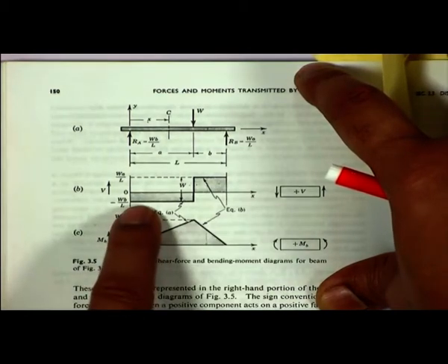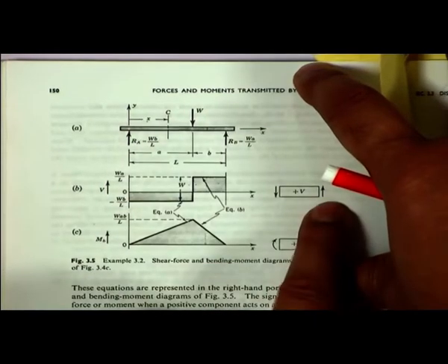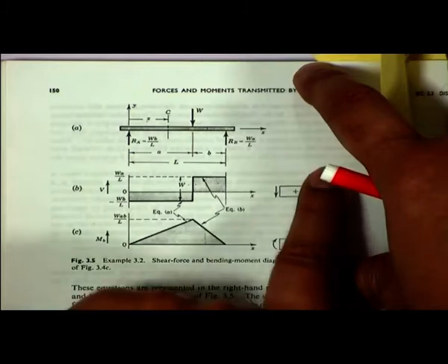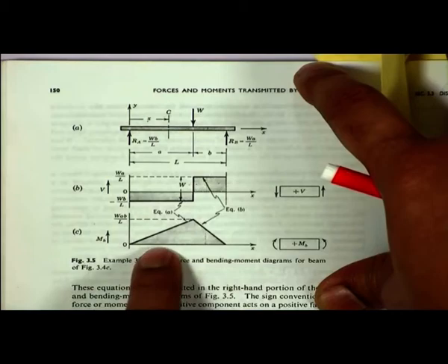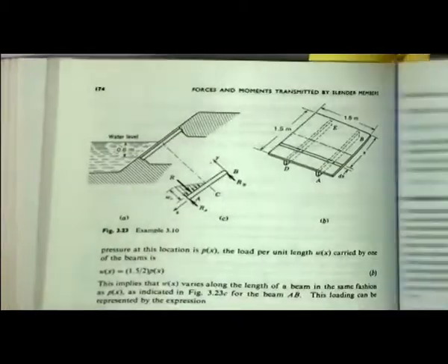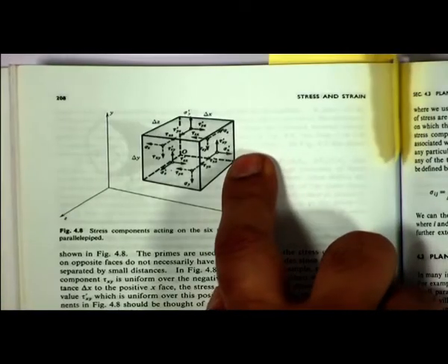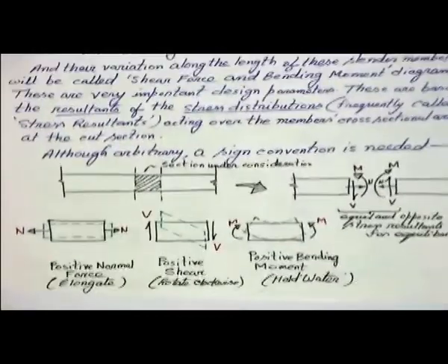It is drawn as negative shear below the line. Similarly, this force which is creating the right part up is drawn as a positive shear force, and this is the bending moment. Probably this is reversed, but it is actually consistent with the figure we have shown earlier. In our cases, we have to follow one of the sign conventions.